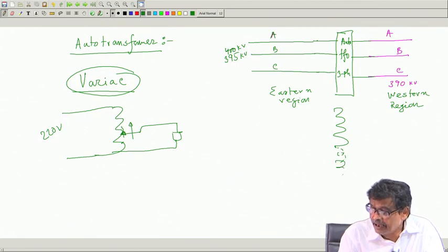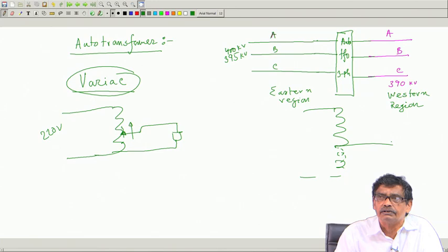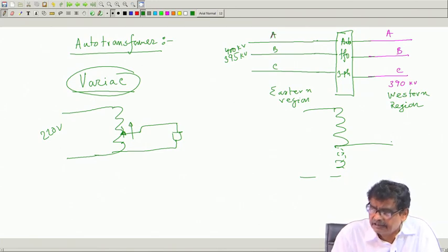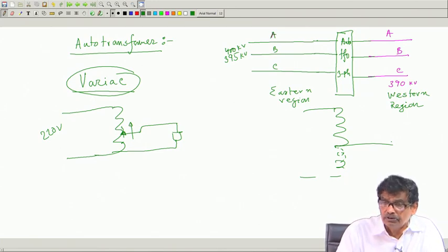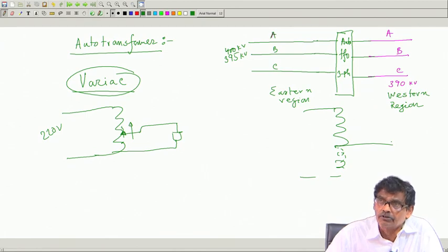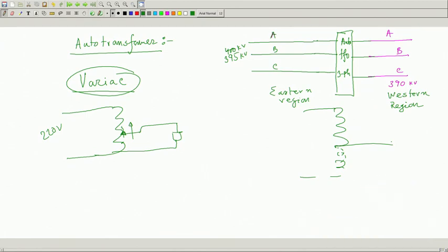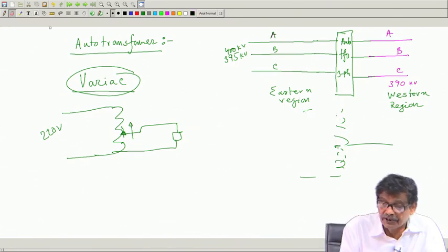This is thinner wire, I drew with different colors, fixed tapping over, nothing like that. This can be moved this way, that way. If you do, you will be taking a lot of risk, you do not know what is the current rating, mixed up current rating of the turns. I hope you have got the point.